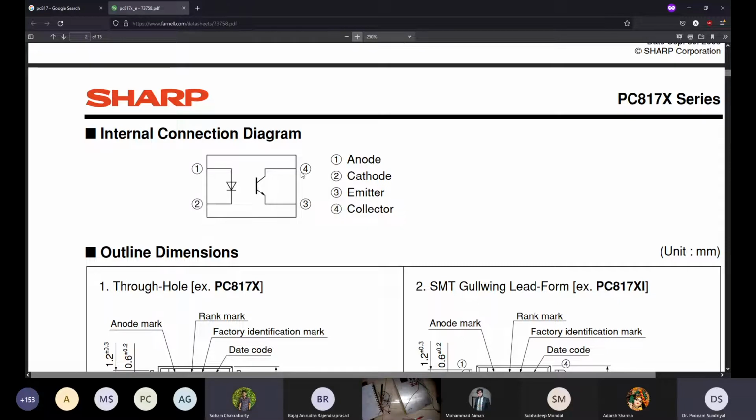But sir, this is a one-sided communication, right? I can communicate from the 1-2 side to the 4-3 side, but not vice versa. So what if I have to communicate from a high voltage side to a low voltage side? Then in the high voltage side there is a ground line, so you have to put sense amplifiers in the ground line. You cannot use an optocoupler to do that task. There are other ways of doing it. The whole point is to not allow 4-3 to communicate with 1-2. The whole point of this is not to allow the cross communication.